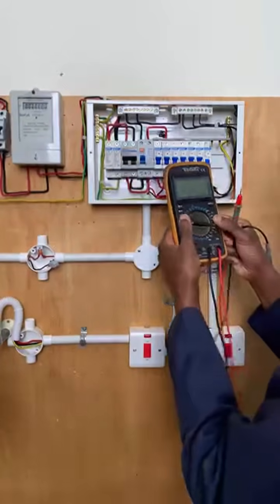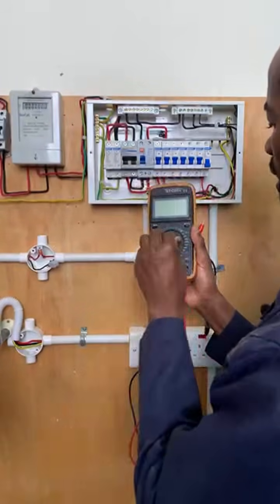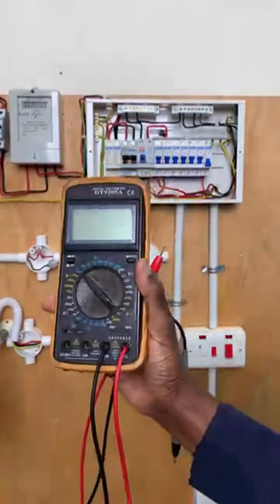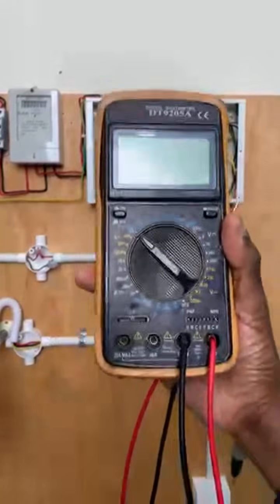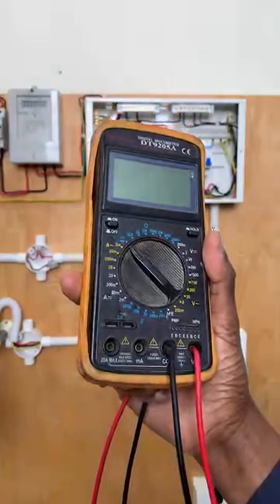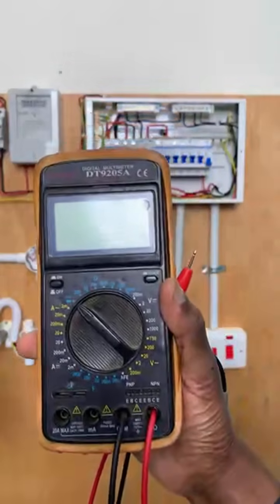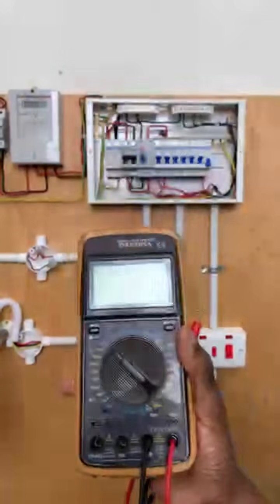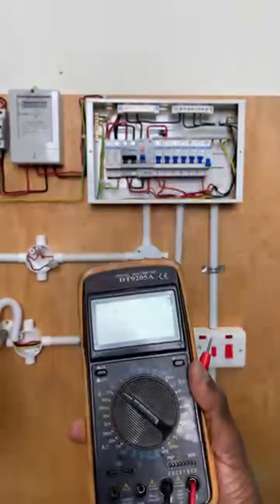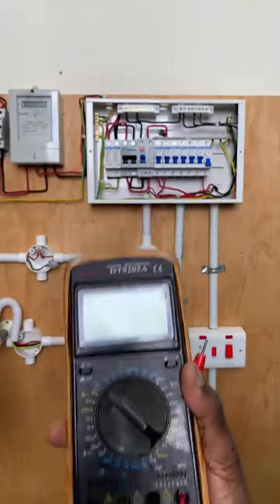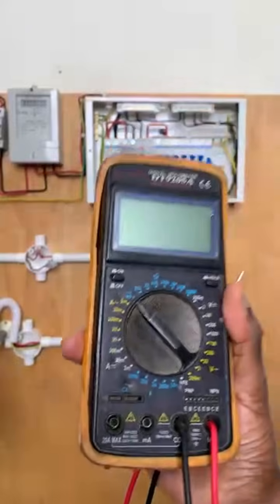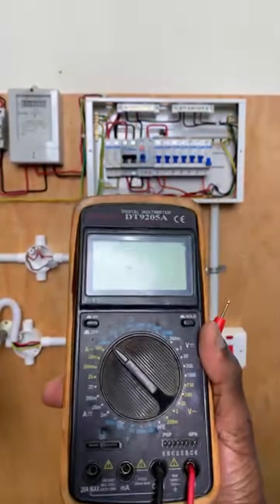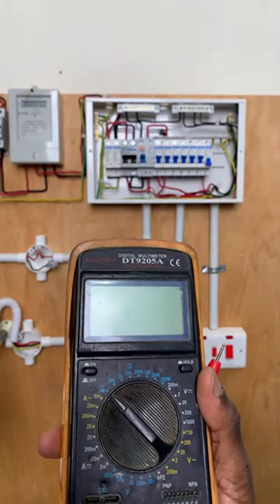Before turning it on, you take what we refer to as a continuity test. At that time, you must ensure that all the lights and switches are off. Why? Switches are off, the MCB is off, but you take a continuity test so that you can ascertain whether there is a short circuit between the output of the circuit that is serving those areas.